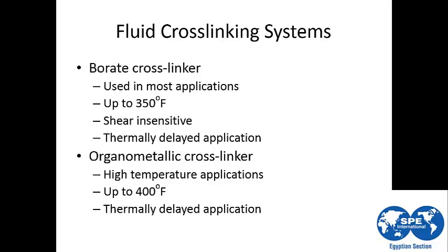So after passing this high shear area, the fracture fluid can heal itself in the case of using Borate Crosslinker. This means that the viscosity returns to its original value after passing this high shear rate area.